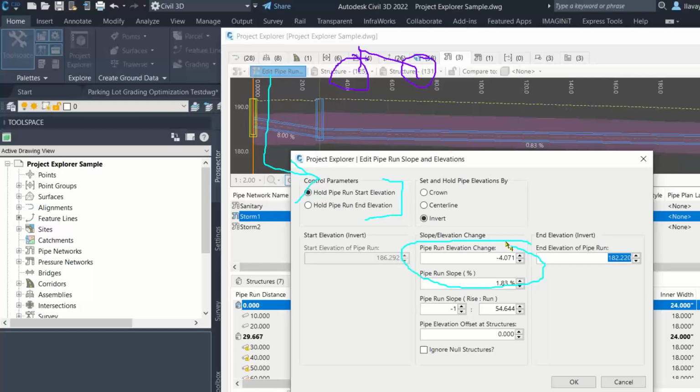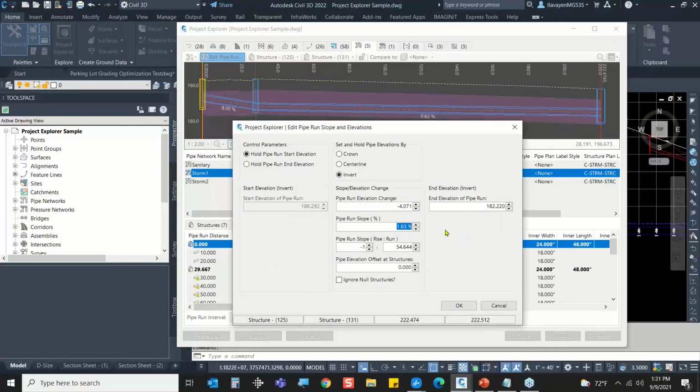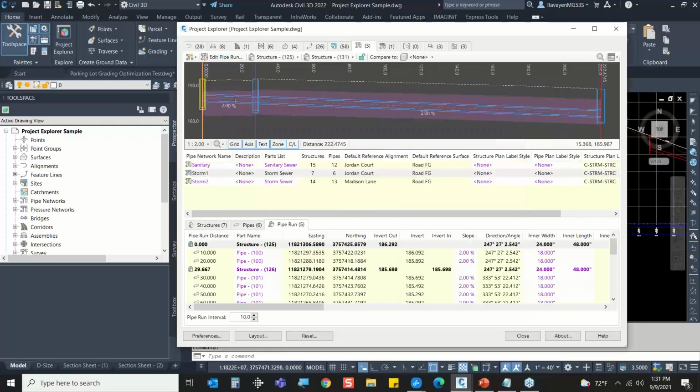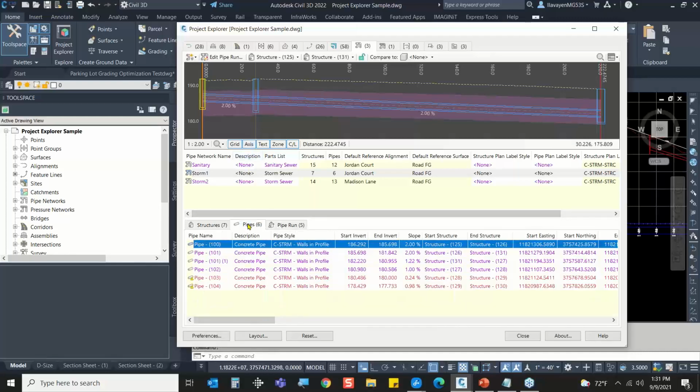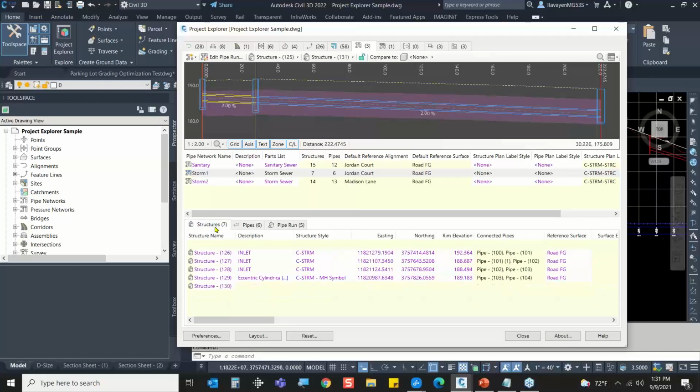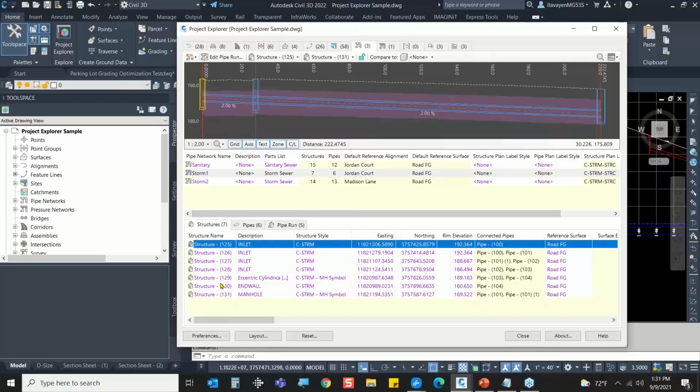Now, imagine just have tool sets that do a very similar result as this, but what I want to do here is perhaps set a slope, and let's set a 2% slope throughout. And all I have to do is hit enter there, and it should then run the math for me. And as I hit OK and exit out, you'll see how that is now designed at 2%. So it allows me to change all these objects at once. And unlike before, where I wanted to perhaps happen to go to each individual object to do something like this, I do have options to talk to these elements all at once. And it's not like the AutoCAD properties tool palette that's limited. This is full on Civil 3D.